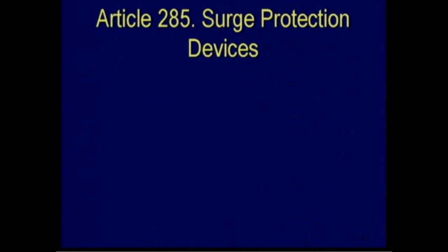You know, I didn't mention this, but AFCI breakers, Cutler Hammer, and I can't say Square D does or doesn't, but Cutler Hammer has a new breaker that you can press and hold for like 2 seconds, and then it flashes, and it shows you the last time it faulted, what the fault was. Was it a fault from neutral to ground? Was it a short circuit? Was it a ground fault? Was it an overload? We're getting devices that are very intelligent and very smart. And so we're seeing energy management starting to work with breakers. So that's an exciting, fascinating field. That's pretty cool stuff. I'm done with 240. Just lightly touched, to get you started inside there.